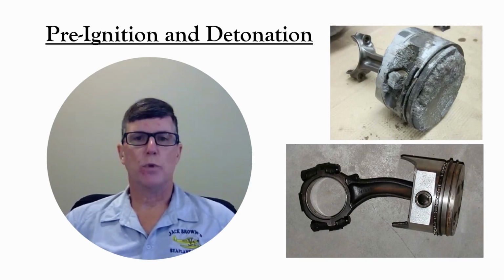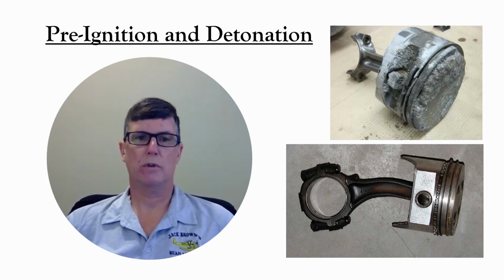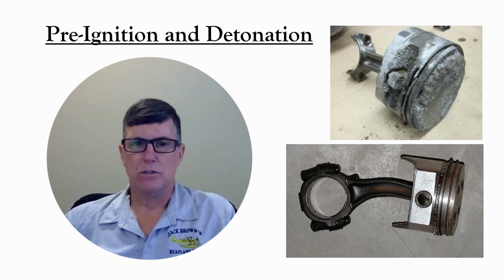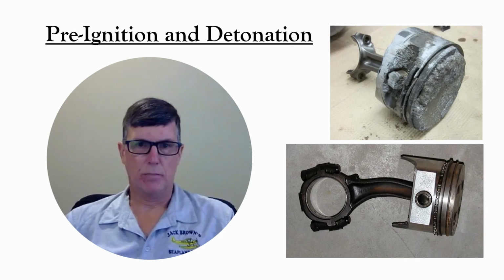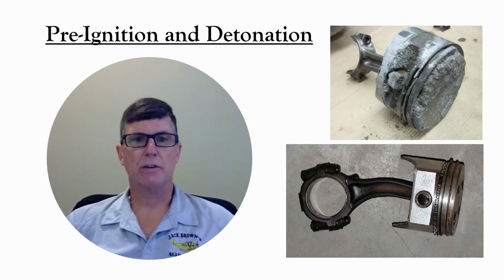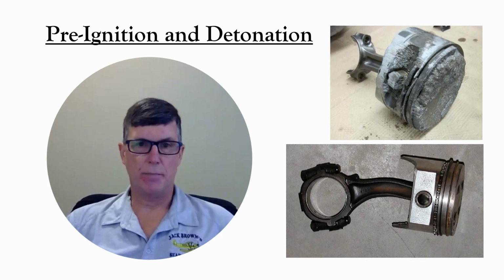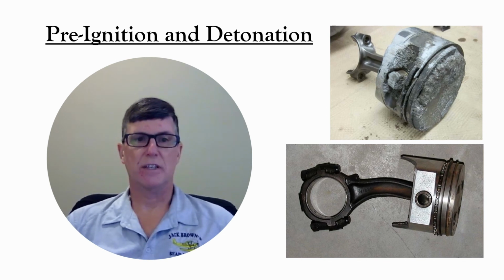Detonation is when the compression itself causes the fuel mixture to explode as opposed to burning gradually. Diesel engines are designed to have compression ignition, but gasoline engines are not designed for that. The extreme pressures that happen in cylinders can cause an engine to fail in minutes. The pistons can literally melt.